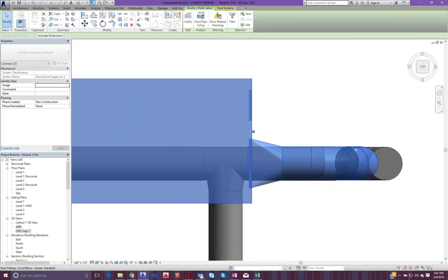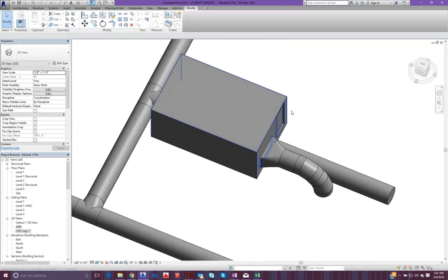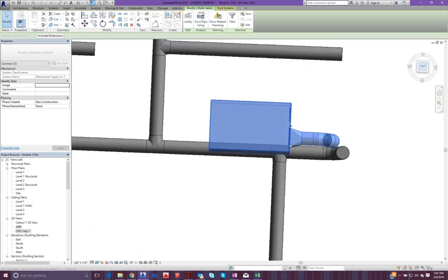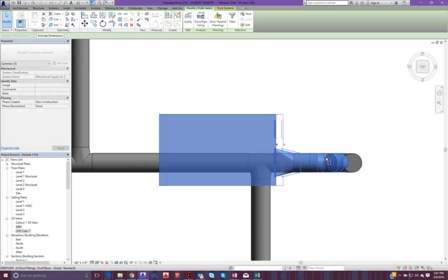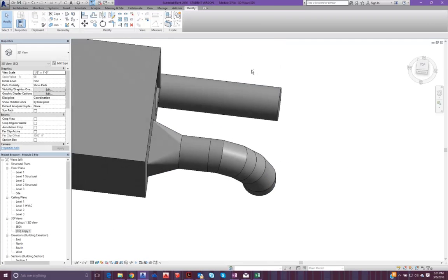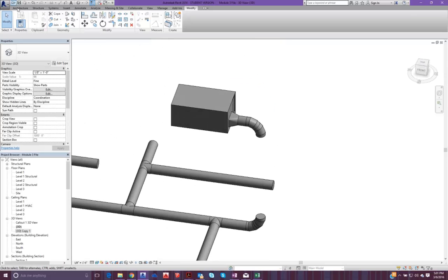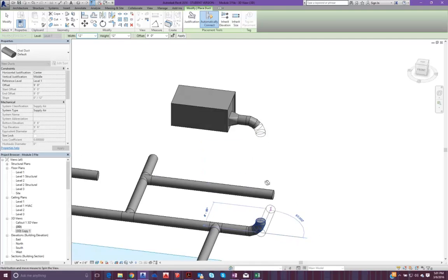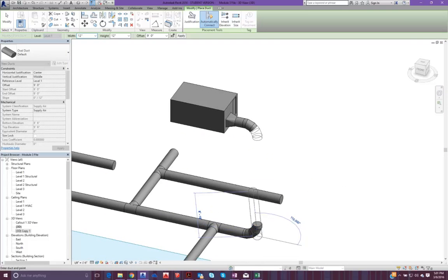And we will move this over to the right to fit with the other ductwork. You can see a line is directly over top of the other. So we'll go to Systems, Ductwork. So automatically connect these, and see if I erase anything, this thing will finally connect.